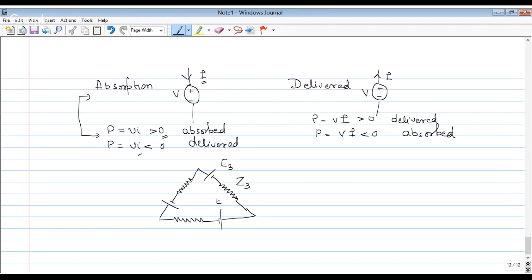This is third harmonic impedance. Now due to this, there will be a current flow in this circuit. EMF 3 times E3 and 3 times Z3. So current will flow E3 by Z3.